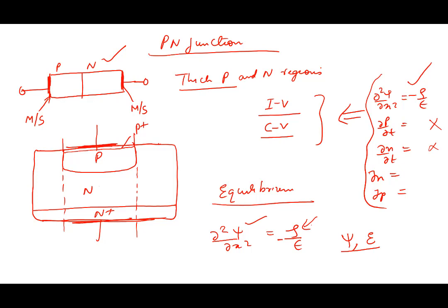Okay, so this is the main equation that one is trying to solve in order to understand the p-n junction in equilibrium. There's no current, but there is still, inside the p-n junction, a potential and an electric field, and that's what you're trying to understand. Now, the band diagram that you draw, one could look upon as a way of qualitatively solving this Poisson's equation.